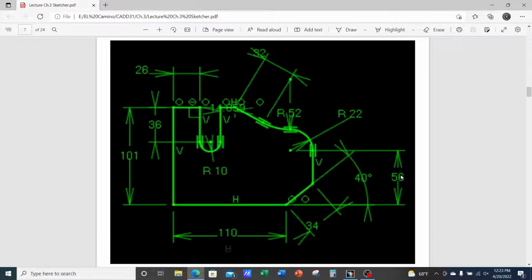Okay, so you can constrain by using dimensional constraints. You can use angles. Once again, anytime you see a ring, that tells you that there's a coincidence. A coincidence can be between a line and an axis, a point and a line. So I'll demonstrate all these constraints.